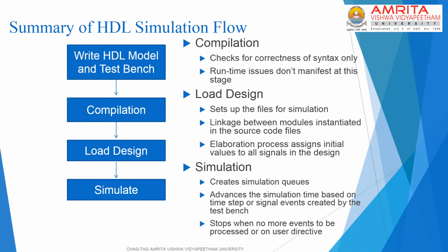The HDL simulation setup will consist of two files, that is the module that is to be verified, which is usually referred to as the device under test or the DUT, and the test bench, which is another HDL file, or it can be in the same file also, which is another module that assigns test vectors to the DUT.